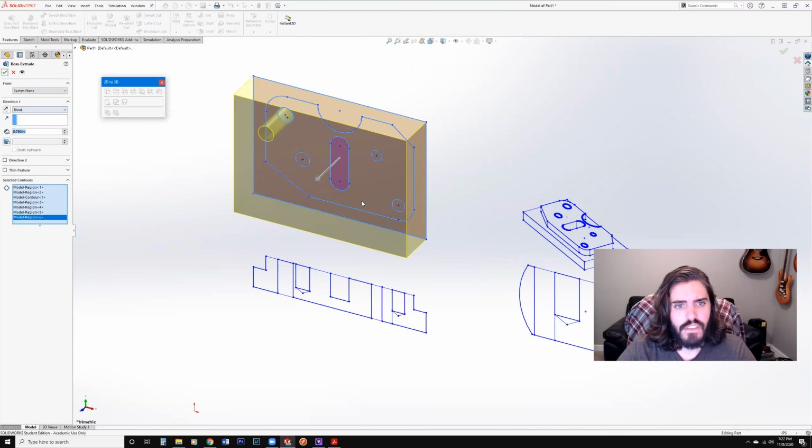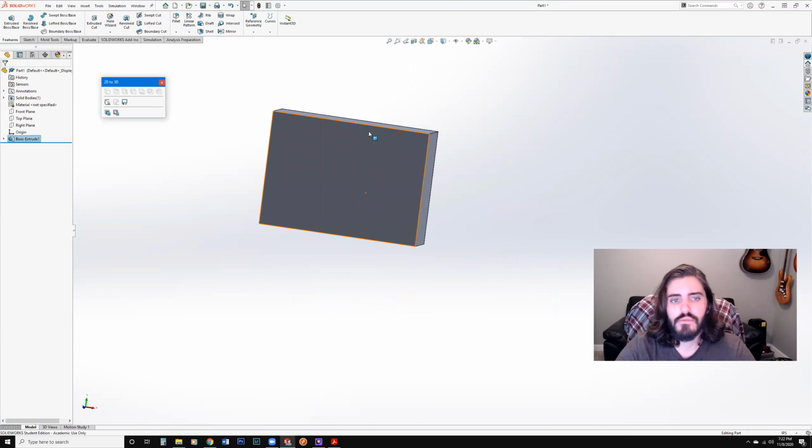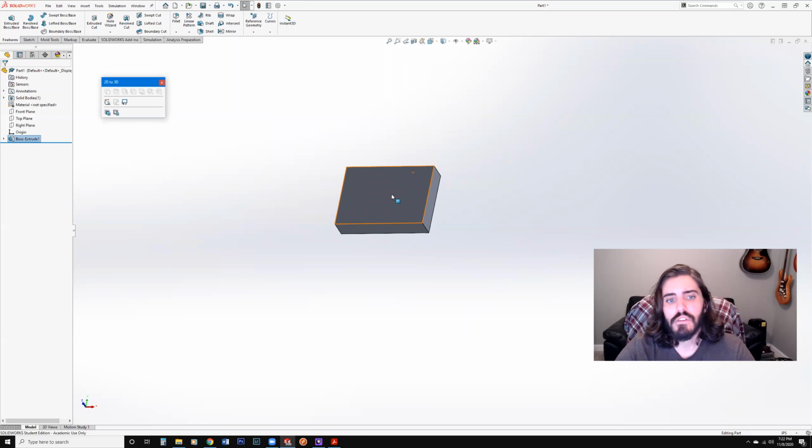You can notice that I don't have to even put in any dimensions, and it's just going to extrude things as such. And I do this a lot too if I ever just need to do something quick, if I need to just take a profile of a forging, or if I need to take some kind of reference file and then revolve it or extrude it. I'll just open the DXF or request a DXF or DWG, and I'll just bring it into a SolidWorks format. And I don't have to dimension it all perfectly, and I'll just extrude it or revolve it as I need.